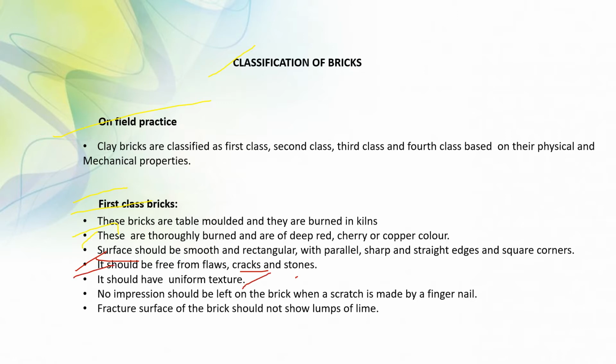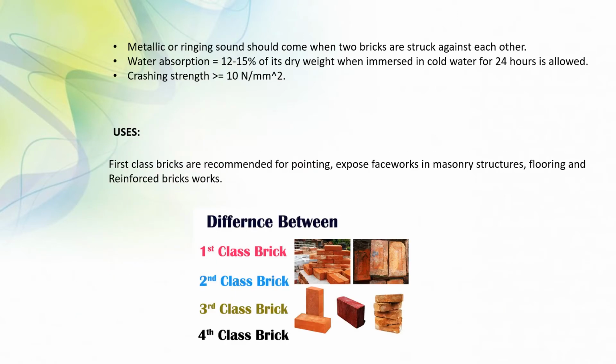This is important: no impression should be left on the brick when a scratch is made by a fingernail. The fractured surface of the brick should not show lumps of lime. A metallic or ringing sound should come when two bricks are struck against each other.